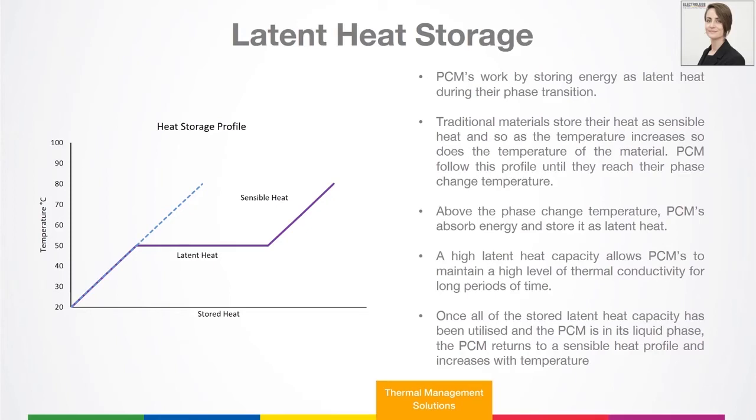They're used to absorb peak energy loads when a device is switched on, and then they release it at another time. So that latent heat is improving the overall efficiency of the device and is minimising the effect of that heat change on the phase change material itself, so that it's always constant and you have much more efficient thermal transfer over the wide and varying temperature range that it's used in.